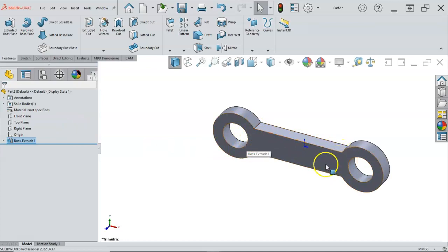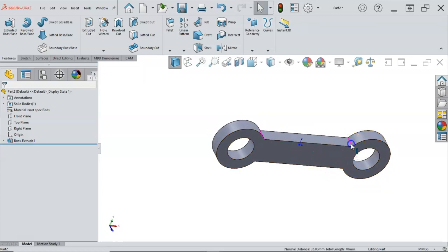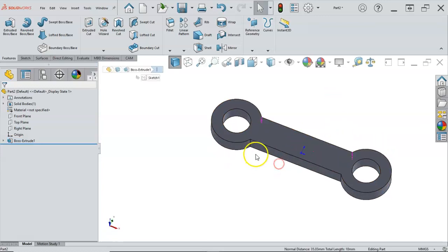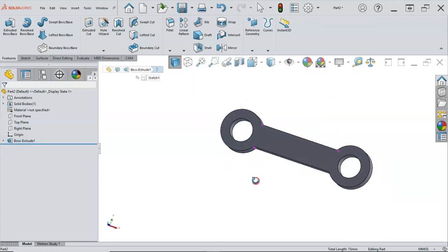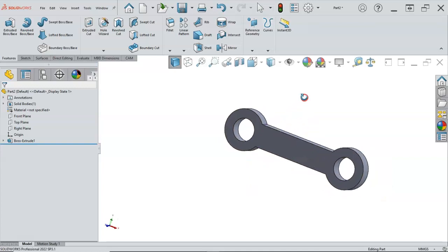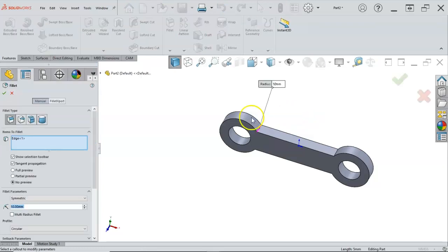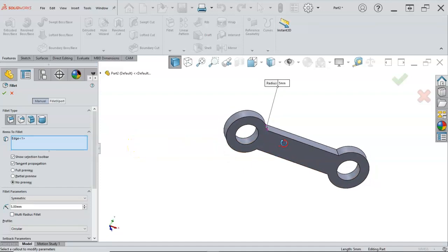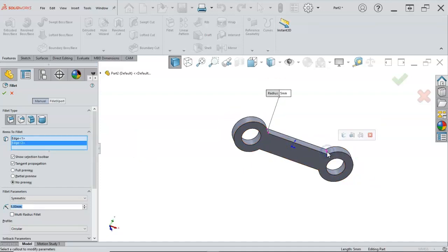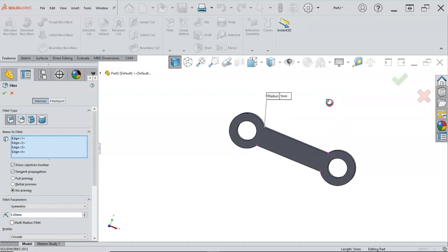All right, so last time I trimmed that out as an example, I wasn't satisfied with, so I'll save that as the optional. And we're just going to make this work. So, this one ought to work pretty good with the fillet selection. I'm already into control select mode. So we go to the fillet on the command manager. We can go fillet the corner. That's going to be a radius of 5. And when I pick the next one, give it a 3 count, and then connect to start.